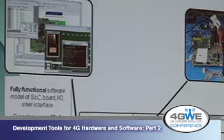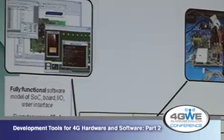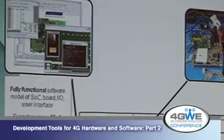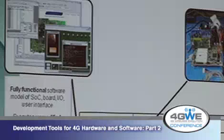The only big difference is, while this is still running at real time, given that it's software and a simulation, I have full insight and full control. So I can stop the processor, I can interact with Chris's delivery, the Tensilica core, the data plane processor, the data plane engine, and stop it at any given point in time and see where my software is at it, so I can look for even things like multi-core issues like races and deadlocks.